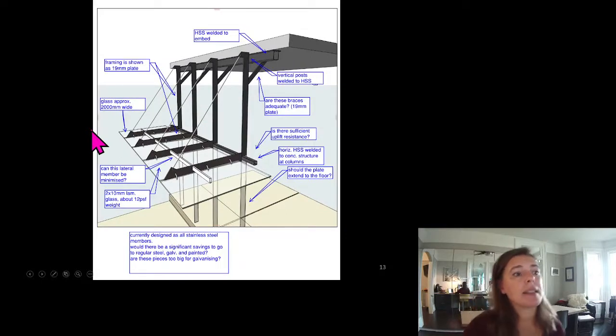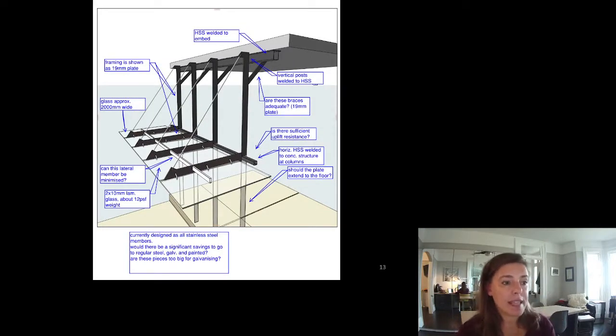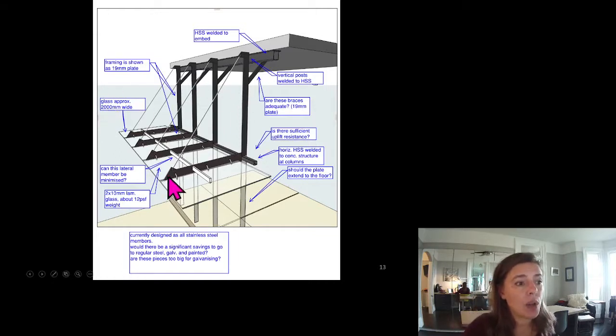So, Via Bloor by Architects Alliance, these were the drawings I was given by the architect. They had a very good intent of what they wanted. They have these cables on them. Architects often add cables here, assuming that it will allow the canopy to be supported here and supported here. And so we have a simply supported element spanning from our column support to our cable support, which is then fastened back here. And for gravity loads, that is fantastic.